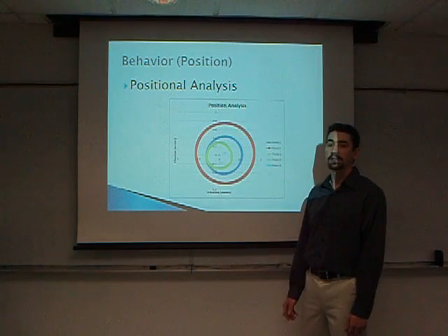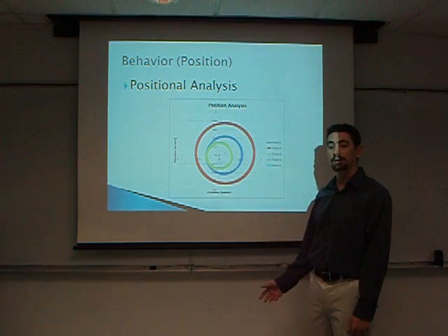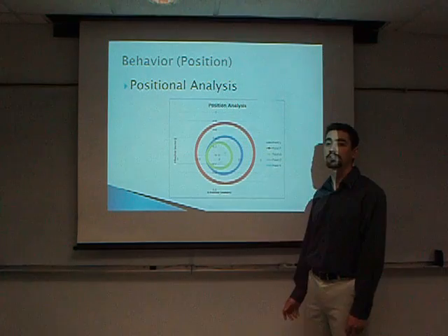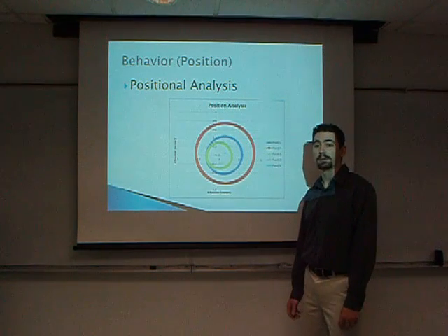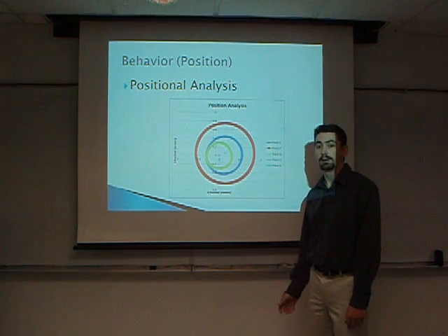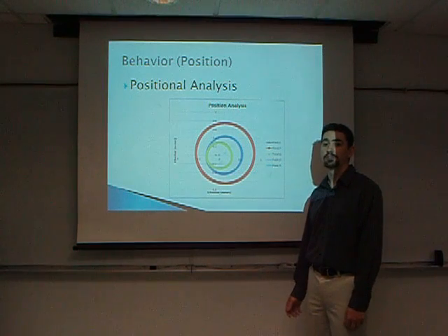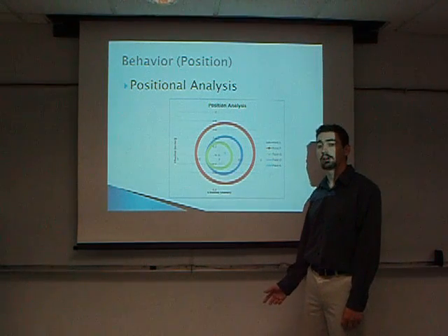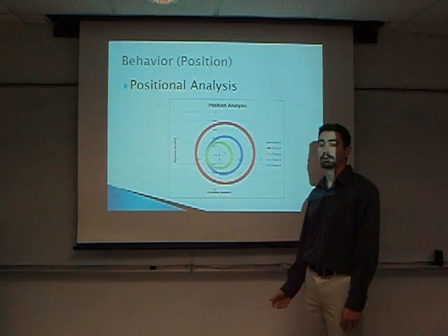As you can see, the paths of R2 and R4 have been traced. Pole positions have also been placed on this graph for your convenience. Point S, a point on the coupler position, is followed and traced along all of theta 2 values with the blue path.